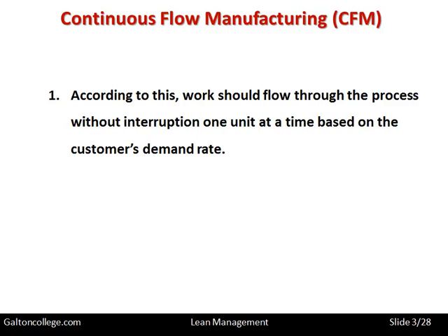Ideally, the raw materials and components should be delivered just in time, so the supplier of the raw materials and the components that are needed should make a delivery at the start of the process, and the raw materials and components should then flow through the various machining operations or the various process operations until it gets to the dispatch stage.